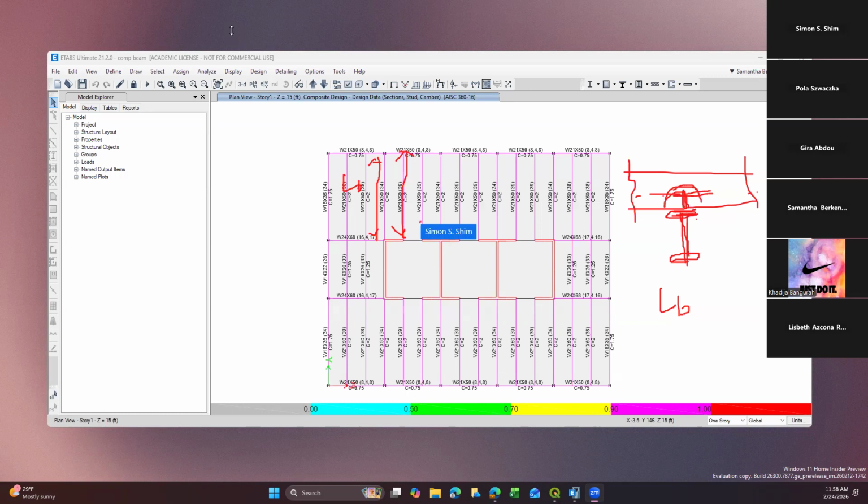Basically, with the studs, the concrete and steel are fully combined, glued together. So this composite connection of studs and concrete is going to provide lateral bracing. So we assume this is continuous lateral bracing, so that L sub b is almost zero or very minor, right? It's the unbraced length L sub b, right?